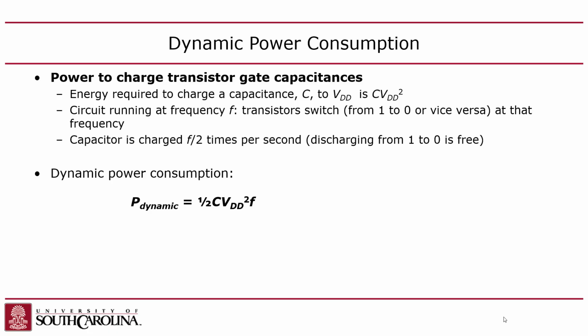It's like potential energy. You actually don't spend any energy until you discharge it, when you dump it all to ground. It doesn't matter which way you think of it. Either way, you only spend energy once. It's either when you're charging the capacitor or when you're discharging the capacitor, right? So for that reason, there's a 1/2, right?